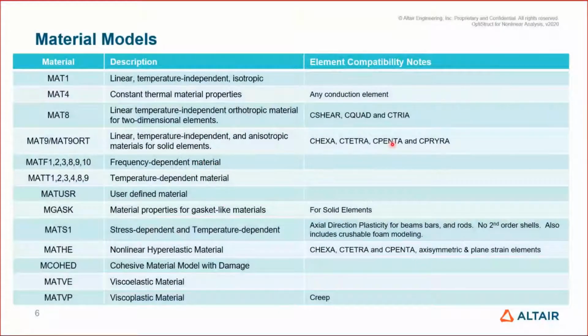So here's a list of the material cards that we have. Nonlinear materials is actually ductile plastic, especially under here, MATS1. And we will also be talking about MATHE. So if you're dealing with hyperelastic materials, rubbers, then definitely need to use MATHE here.